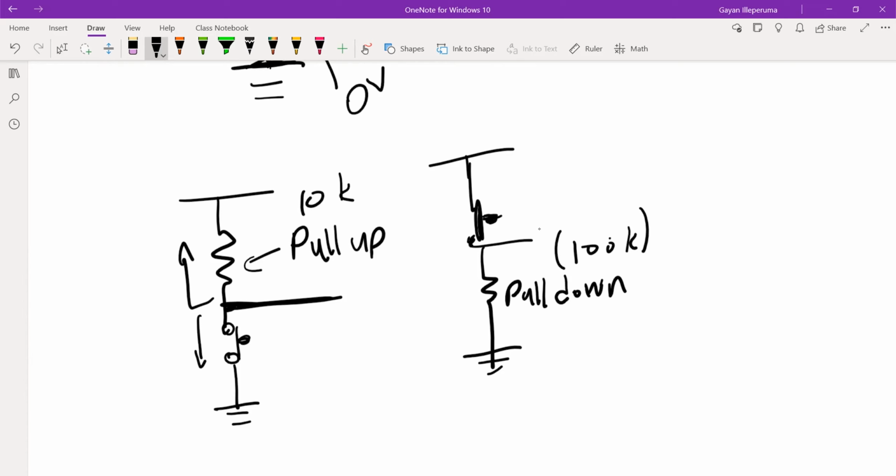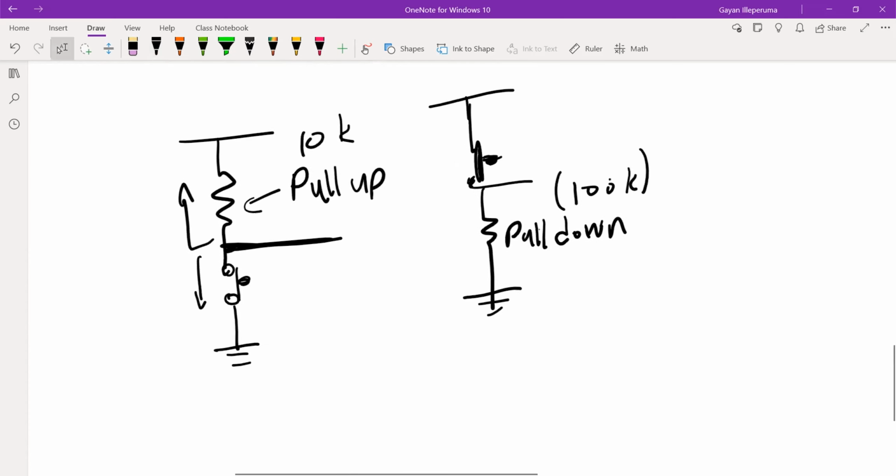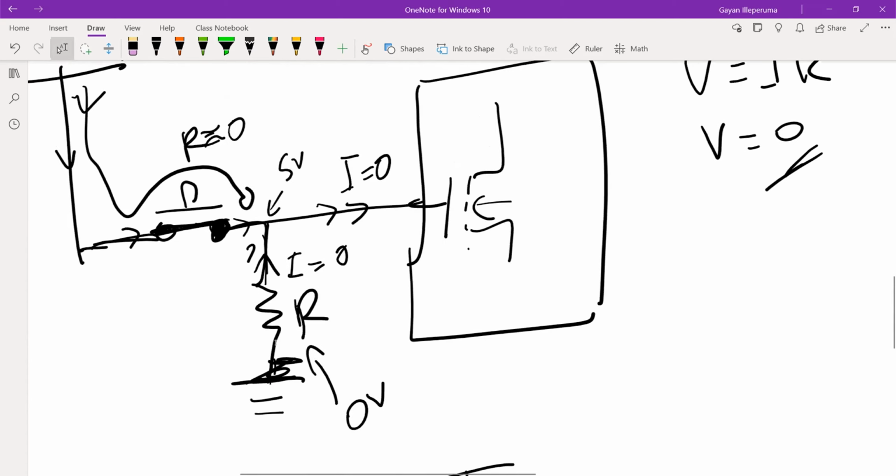So when you are designing a project, when you have switches, make sure you follow this. Otherwise, you will face certain logical problems that you will never be able to identify, because your circuit starts behaving so illogically. Sometimes without the pull up, if you have another circuit wire going very close to here, this voltage might affect this voltage. So from time to time, it starts working in completely random ways.